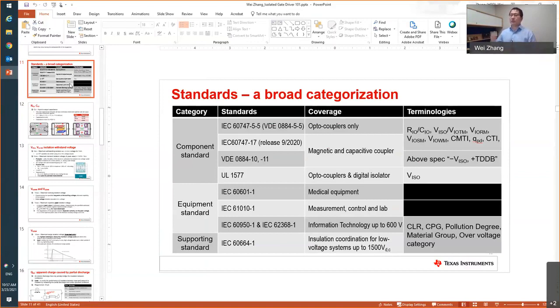with more vendors and more competitors coming to the market, ISO drivers are being standardized for high performance converters. Everyone is using ISO drivers to achieve high performance, better skew, higher CMTI, and what I can find now is that every silicon carbide and gallium nitride design is using ISO drivers because of the performance. And for high frequency, you do not want to use opto because the jitter, the pulse distortion, and the degradation of the LED all suffer a lot. So a lot of advantages. We also have a lot of collateral supporting them.